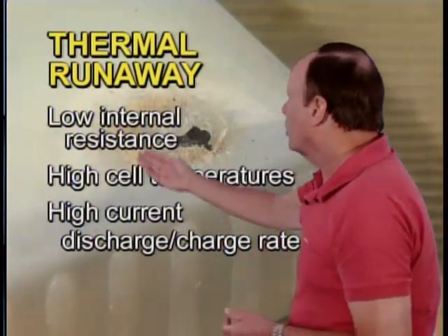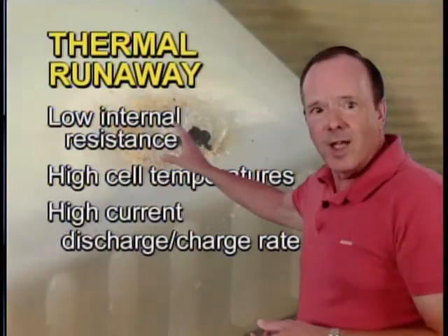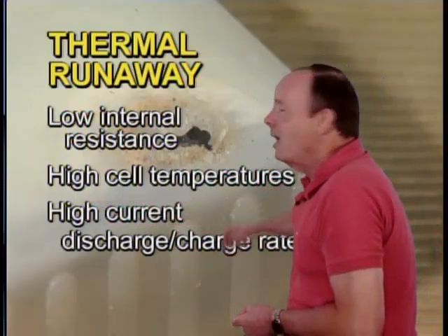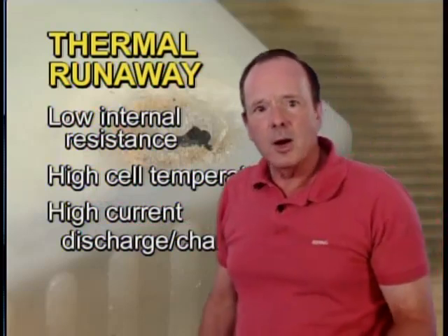So what contributes to thermal runaway? Well, the low internal resistance of the battery is one factor, and of course the resistance gets even lower when you have high cell temperatures. And finally, the charging system in the aircraft makes a difference.